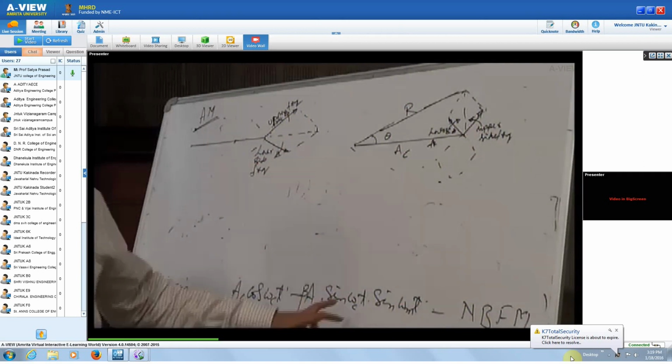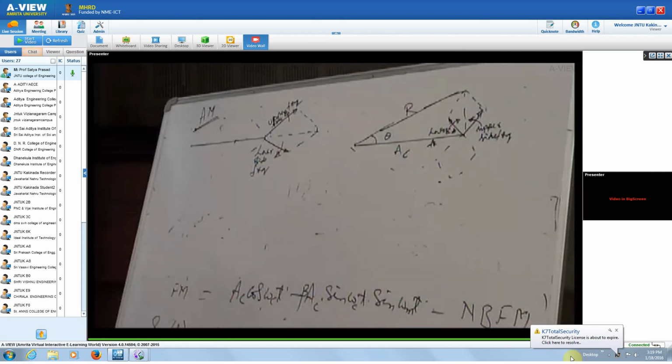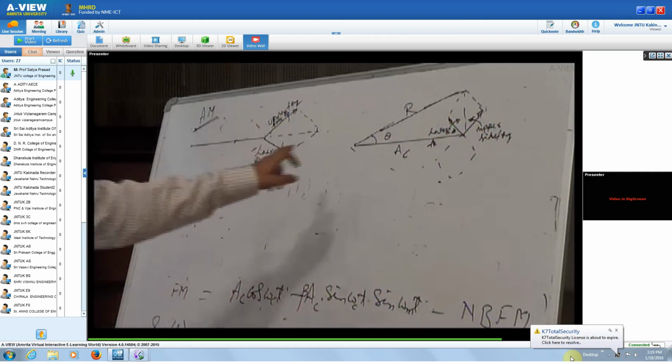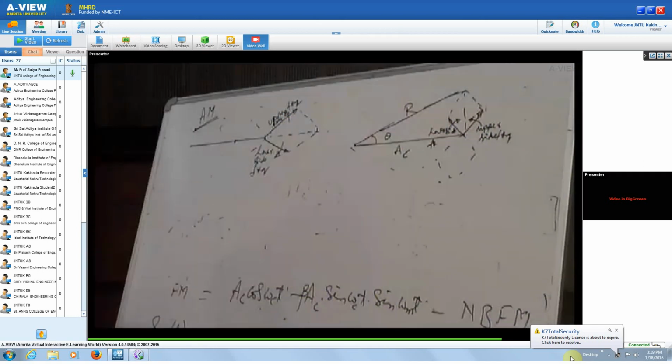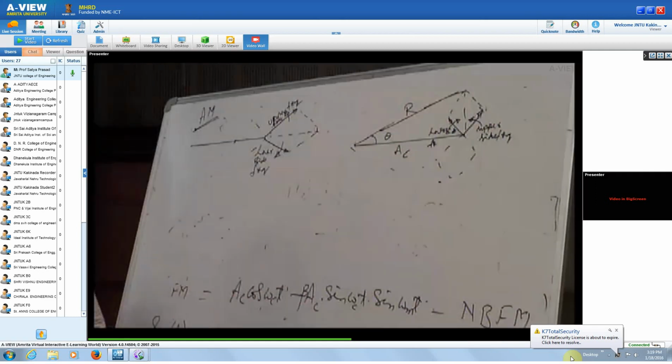And not only that, you are going to have the third harmonic also in addition to our first harmonic Fc plus Fm and Fc minus Fm. The third harmonic also is going to be there in your signal. Therefore, as I said, we'll use it for generation of wideband FM in the indirect method of generation of general FM signal, which we are calling a wideband FM. This is the narrowband FM signal.